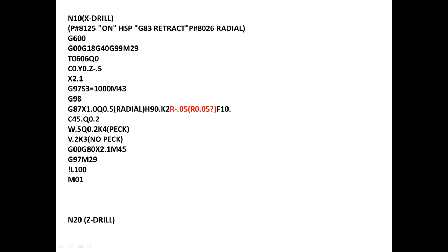So now C2 is zapped in as 0. Now when we go to use spindle synchronization and cut off, we have to use the proper code and syncing methods, and M203 is the spindle synchronization code, and a little argument R0. You got to make sure you have the R0.